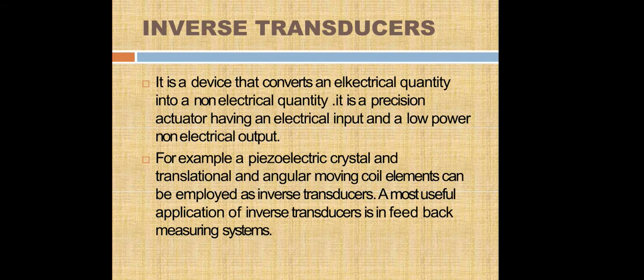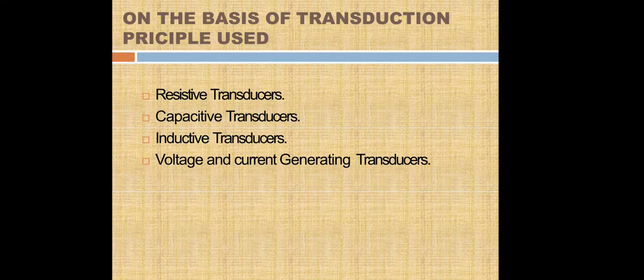Inverse transducers. It is a device that converts an electrical quantity into a non-electrical quantity. It is a precision actuator having an electrical input and a low power non-electrical output. For example, piezoelectric crystal and translational and angular moving coil elements can be employed in inverse transducers. A most useful application of inverse transducers is in feedback measuring systems. On the basis of transduction principle used: